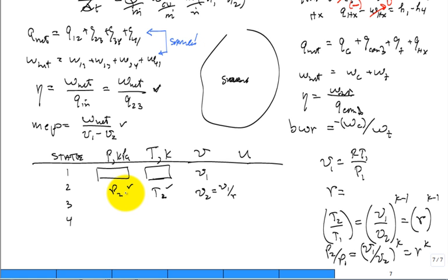So you're jumping back and forth, getting these pressures and temperatures. Either they're told, you're given some information. A lot of times they'll say the maximum temperature in the cycle is, well, that's T3. Or the amount of heat added is so many kilojoules per kilogram. Go back to the first law for the process 2 to 3 and then calculate T3.